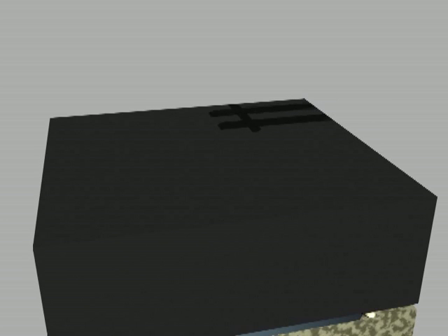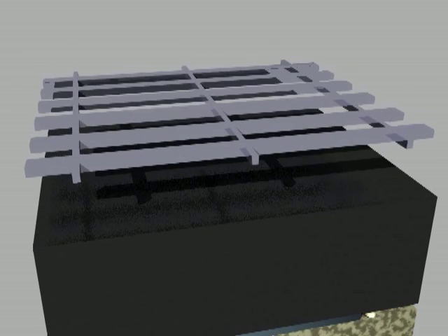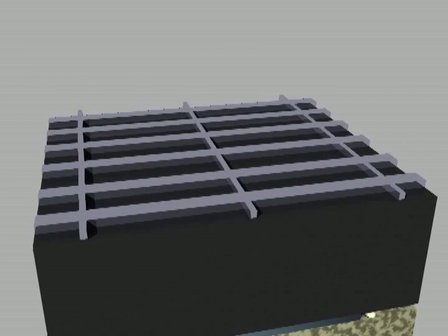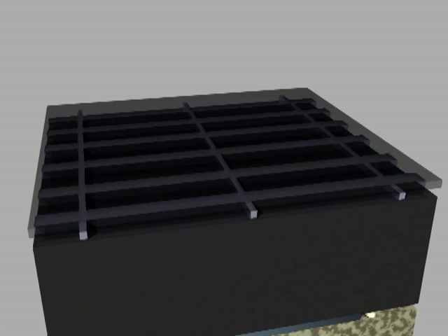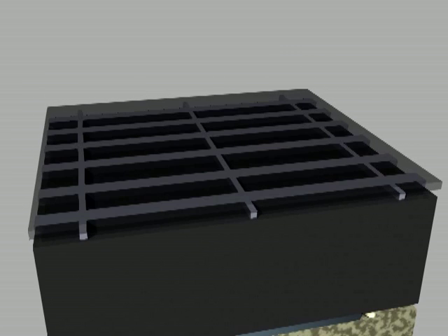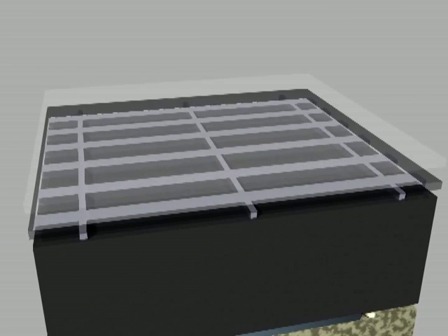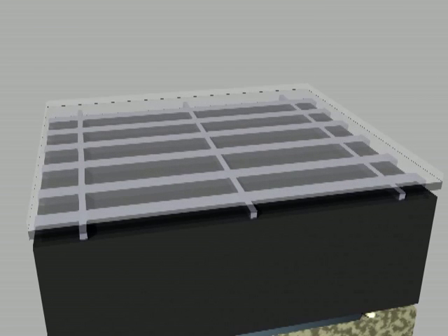By replacing the top contact with a fine metallic contact grid, this shortens the distance that electrons have to travel and reduces the number of photons blocked by the contact itself. Also, as silicon is a shiny material, an anti-reflective coating is added to the top of the cell to reduce losses of energy caused by reflection. Finally, a glass cover plate is added to protect the cell from the elements.